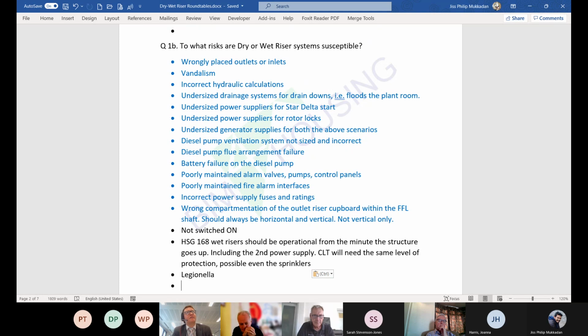No, and I think to put it this way, right? This is how we used to operate a long while ago. If you've got a drawing put in front of you and the consultant's not warranting the pipe size, then just take it off, because people will go away and try and install it. Because you have to work on the basis that design is a big word. It's misinterpreted, and an approximate design isn't the actual design. So you might have a sprinkler schematic and some stuff on it for tendering purposes. It doesn't mean if you install it, it's going to work.